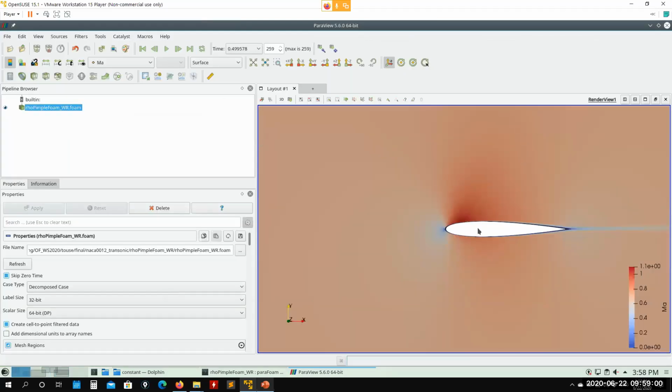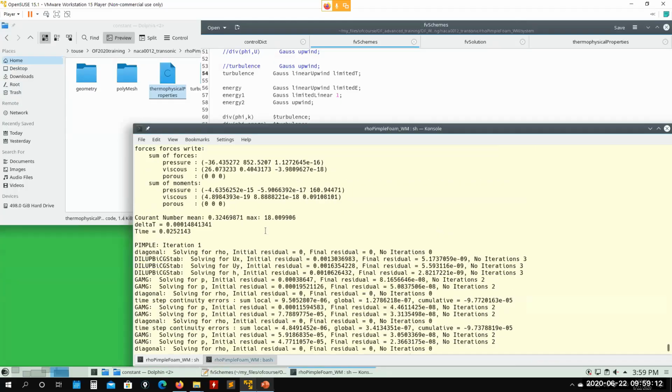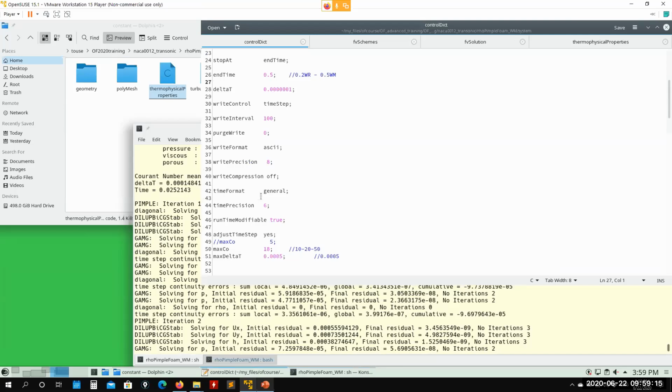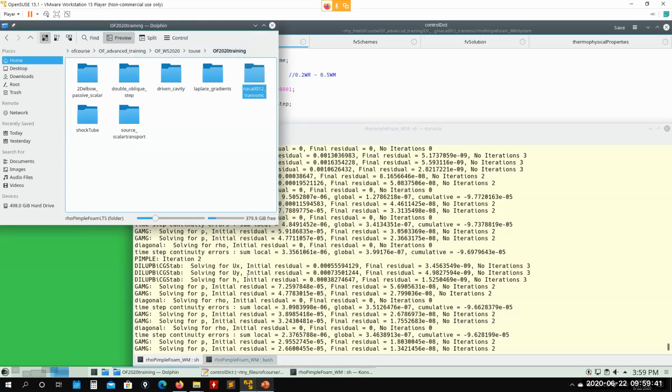So in this case, on 4 cores, it will take about, if I recall, 1 hour to run. So I think I am just in time. Okay, so see that this one is 18 and you can go. So feel free to play with this case. I tested, and it can run up to CFL 40, or 50, with no problem. But again, you are missing a lot of accuracy. So that is not the idea, okay? And a lot of people want to get solutions right away. You will lose accuracy. Okay, so I think with this, I'm sorry that I didn't cover everything, but I hope you have an idea. Okay.